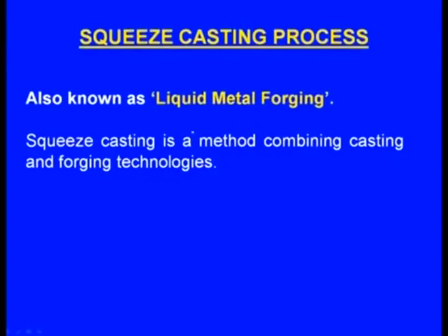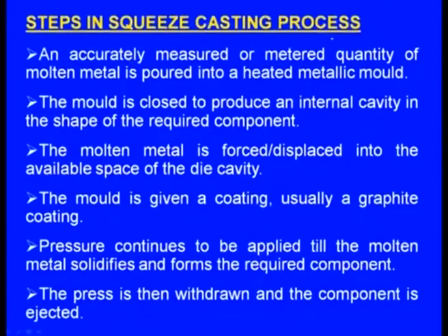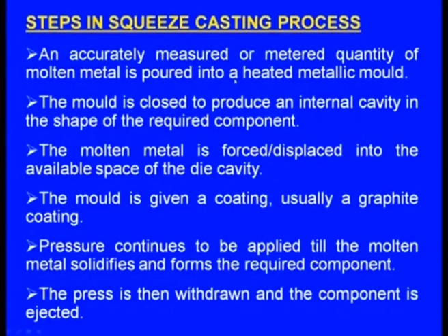Squeeze casting process is also known as liquid metal forging. Squeeze casting is a method combining casting and forging technologies. What are the steps in the squeeze casting process? An accurately measured or metered quantity of molten metal is poured into a heated metallic mold.